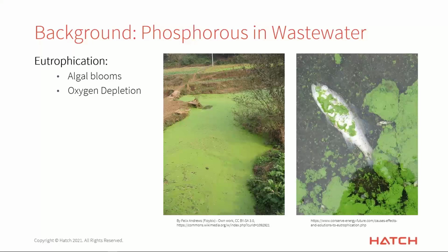So we all learned many decades ago that wastewater treatment is important and biological nutrient removal is important because we want to remove the phosphorus in the loading that's coming to the system. In many places in North America, they have reduced over the years the amount of phosphorus that is present in detergents in order to help prevent this problem. But whatever is left over that goes down the drain in the wastewater needs to be dealt with when it gets to the wastewater treatment plant, either through chemical means by precipitating it out or by doing biological activity, which is what we're going to talk about today.